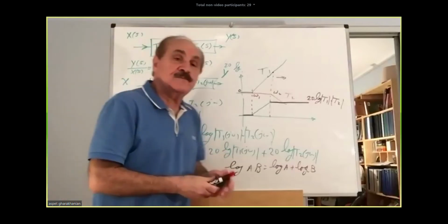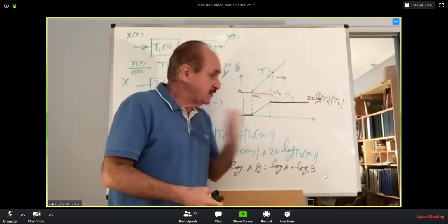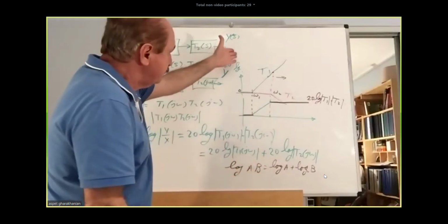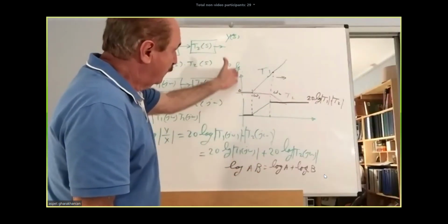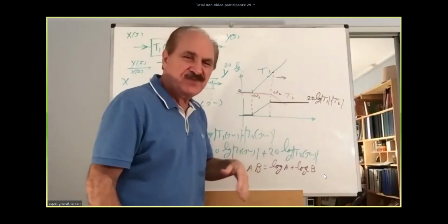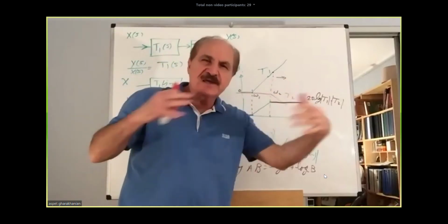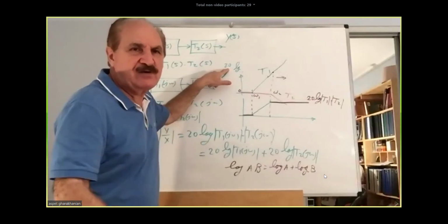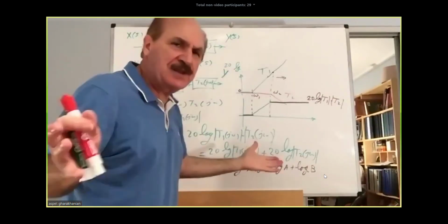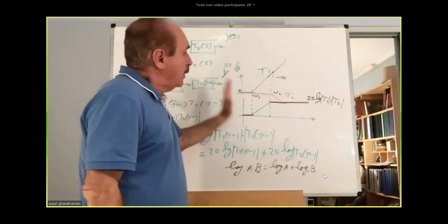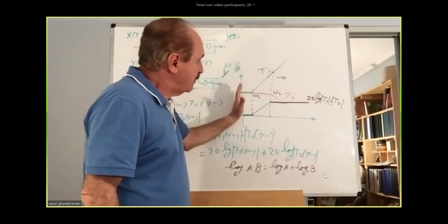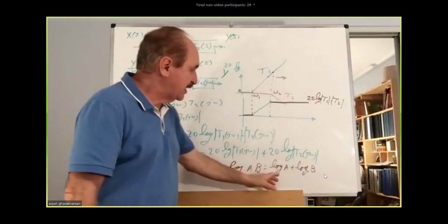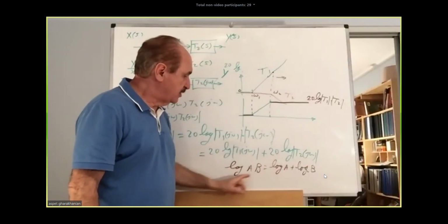So the greatest advantage of this logarithmic concept, plotting the logarithm of the gain against the frequency and scaling it with a multiplier of 20, that is just the multiplier of choice, 20, just standard. The addition of these logarithmic verticals together is equivalent of multiplication, logarithm of the multiplication.